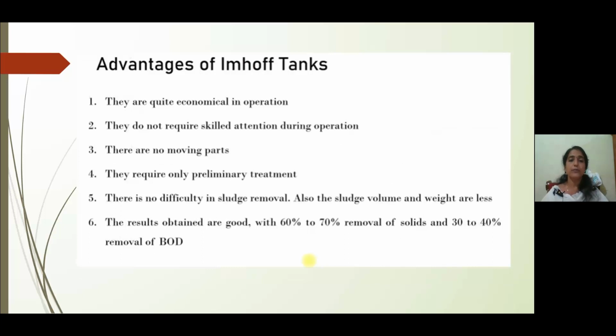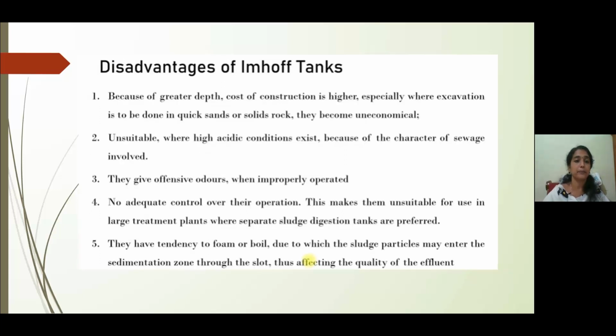Then the advantages of Imhoff tanks. They are quite economical in operation. They do not require skilled attention during the operation. There are no moving parts. They require only preliminary treatment. There is no difficulty in sludge removal. The desludging process is easy. Also, the sludge volume and weight are less. The results obtained are good, with 60 to 70 percent removal of solids and 30 to 40 percent removal of BOD in an Imhoff tank.